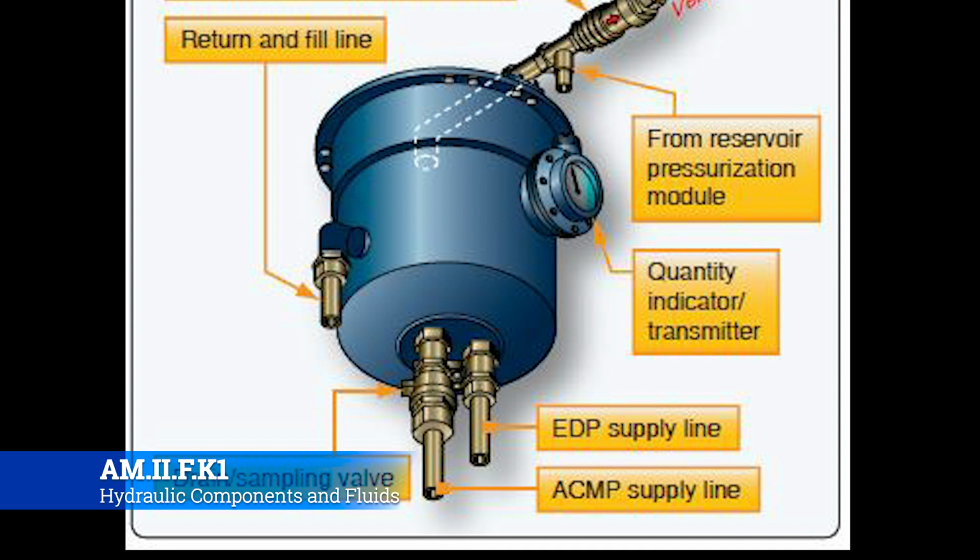Now, we haven't got to fuel systems yet, but this is something that's really common on fuel, is that you'll sump the system every single time that the aircraft either goes to fly the first part of the day or gets fuel. So the sump valve on a hydraulic system works much the same way. You'll be able to go up there, pull a sample out, and make sure that all the trash is out of it, and that there are no metal flakes in it or anything that could potentially cause a system failure.